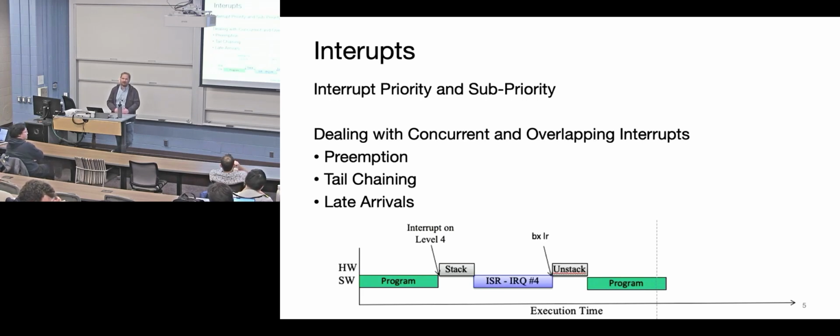But something with the same priority will not interrupt itself. So if two interrupts have the same priority, the new one is not going to interrupt this one. It's going to be in the pending queue. So say you get 4 things that all have the same priority, they're going to be put on the pending queue. Now, when the NVIC exits its current interrupt, which one does it choose to do? It looks at the sub-priority bits to figure out which one should go first. Did I say that confusingly enough?